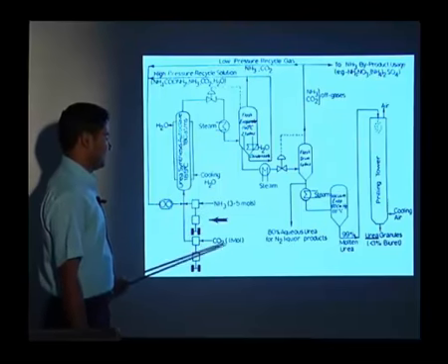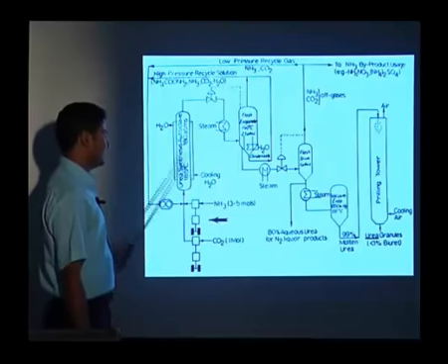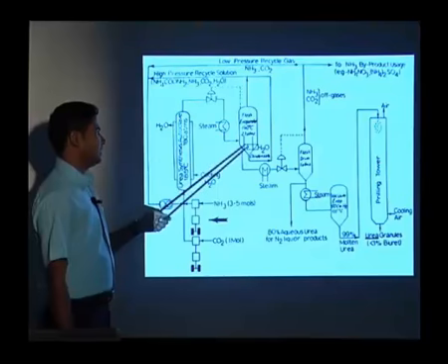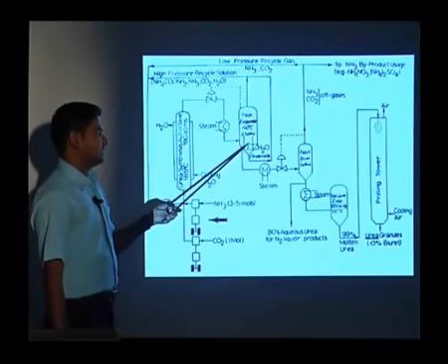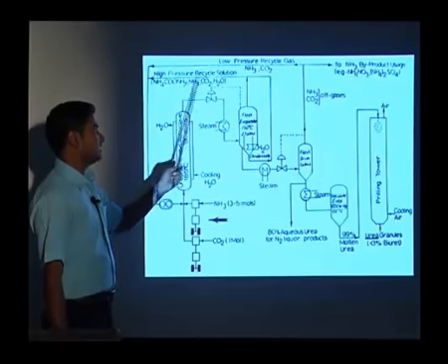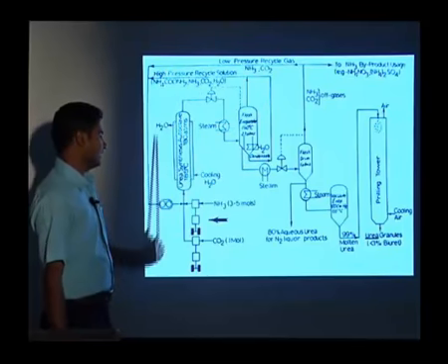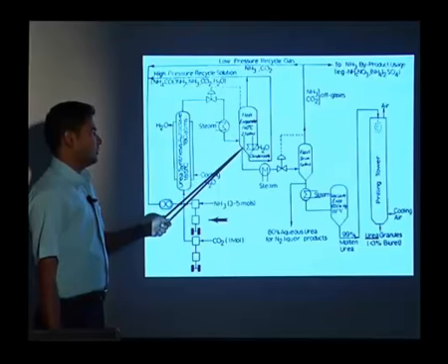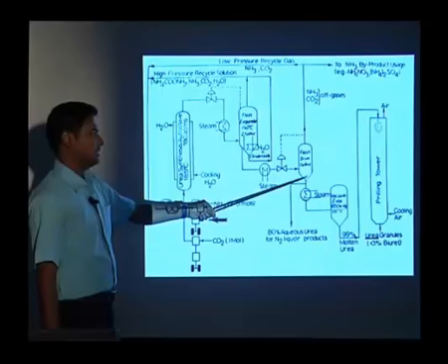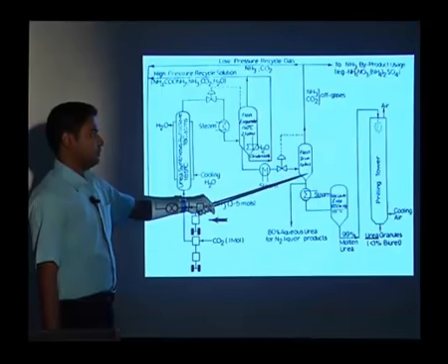So here CO2 and NH3 are separately compressed and fed to the reactor for 1.5 to 2 hours, which gives the ammonium carbamate. Here the unreacted gases and ammonium carbamate are separated. The condensate and the unreacted gases are sent back to recycle, and the ammonium carbamate is again sent to the flash drum, where it will decompose to urea.